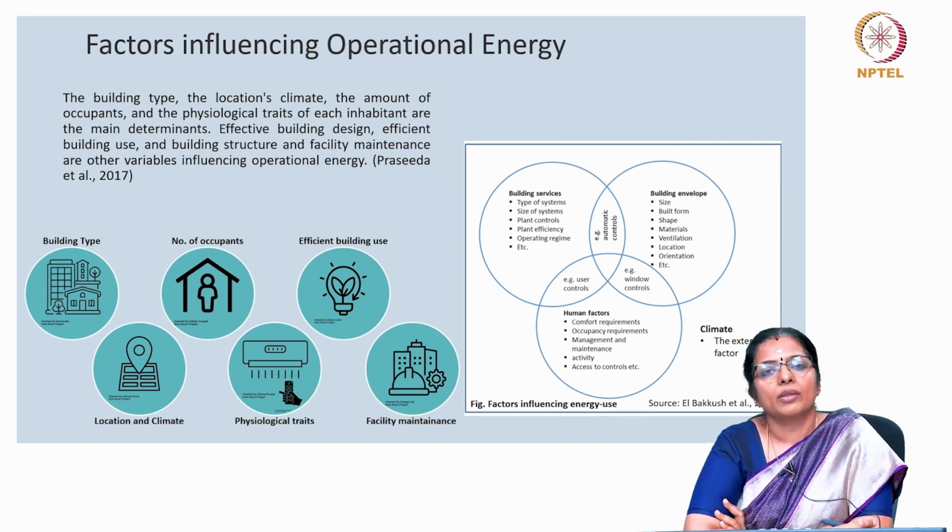For example, how many of us care to clean the air conditioning filter regularly? Only when we sense a dip in its efficiency, we make that effort. But that also increases the load on the air conditioner. I am not talking about the impact it has on the indoor air quality. So, maintenance of equipment is also a very important criterion. Only then we will get its peak efficiency. All these collectively contribute to reducing the building's energy footprint.